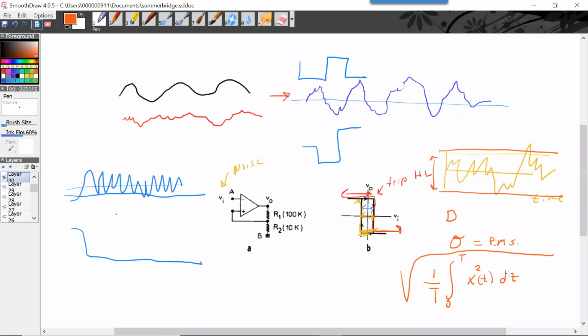in the circuits course, we go over this calculation for things like square waves, triangle waves, and other such things. Now the noise is kind of random, right? And so you don't really know how to integrate it. What you do is you just numerically square everything, sum it up, and divide it by the number of points.